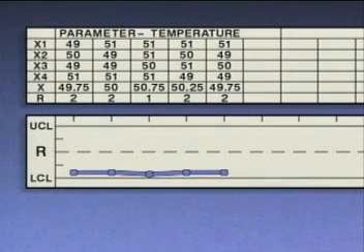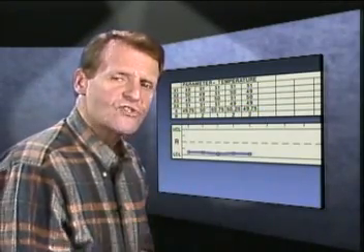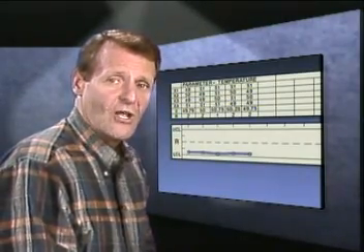According to the laws of probability, there's not enough variation occurring in this process. Indications of low variation should be investigated to see if a problem exists. To determine whether a low variation is abnormal, you need to understand the process and to know how much variation is normal for that process. As you can tell, when X-bar charts and R charts are used together, they provide a more complete picture of what's going on in a process.